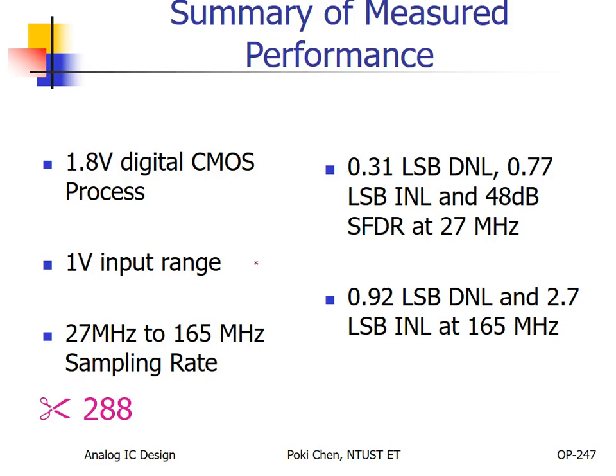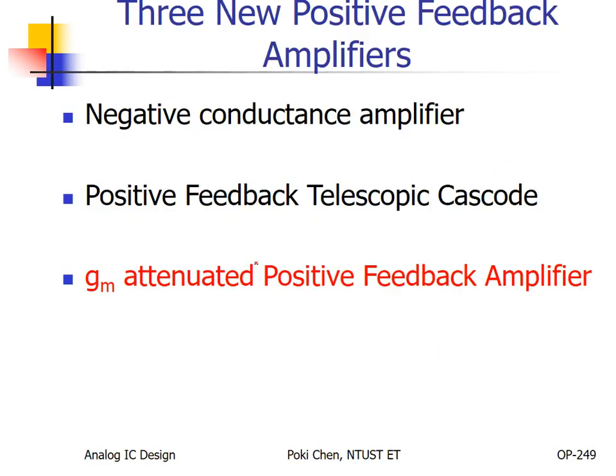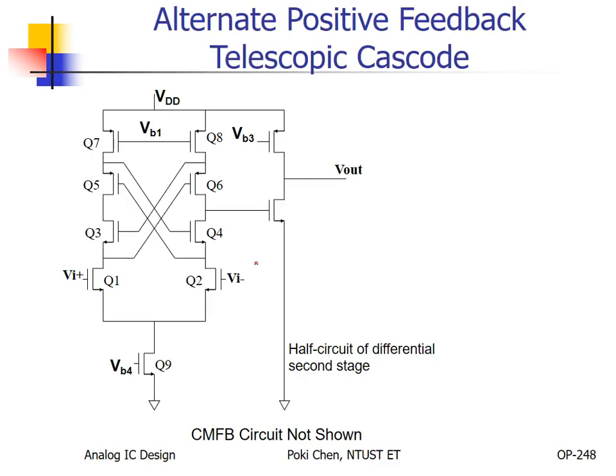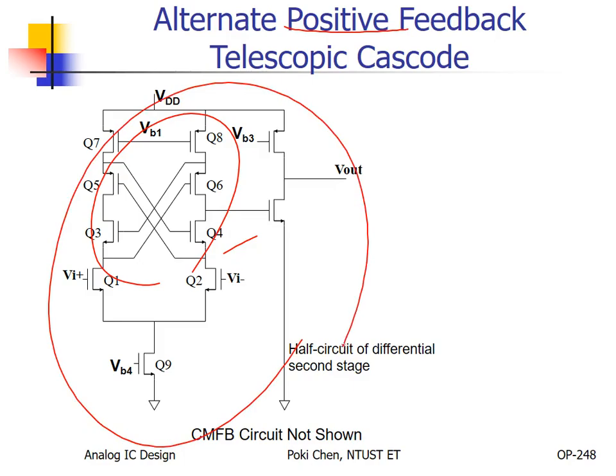All right, and what else can I help with? I think I finished. Oh, yeah. See, that is an even crazier idea, right? If you would like to enhance the gain further, you can have double cross connections to apply more negative impedance to get much higher positive feedback. Wow, you can achieve much higher gain. But what is the cost? What is the price you need to pay? It is even harder to stabilize the overall circuit. Again, even harder to make every transistor operate in the saturation region, to be honest. Okay, so nothing is free. You need to pay for your hard work. Yeah.